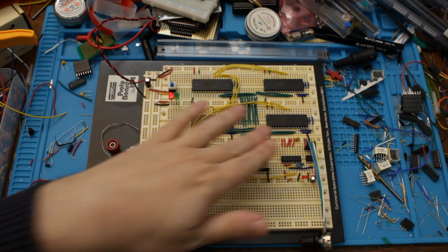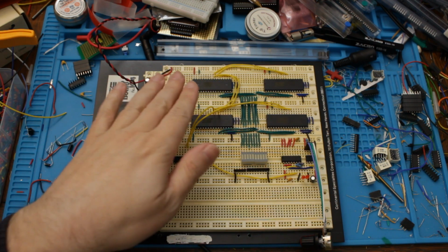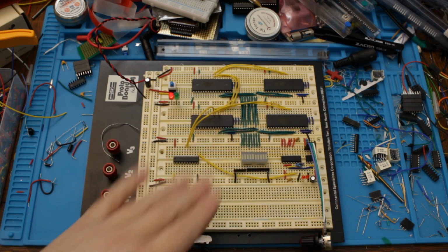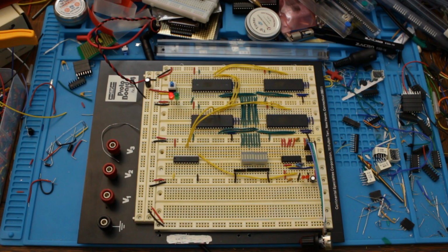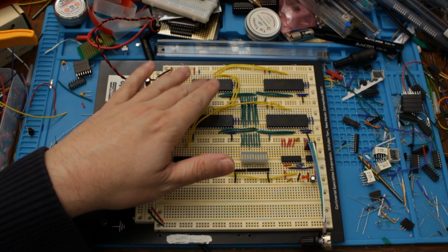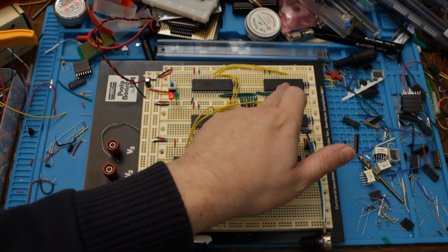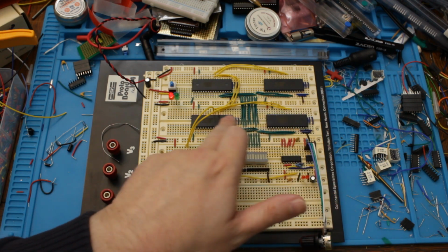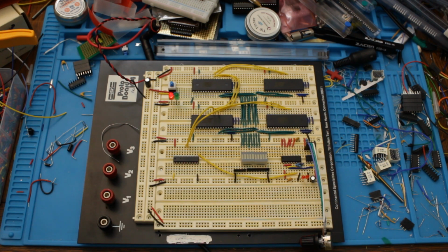As for the EEPROMs, I have pre-programmed them so that each EEPROM has 1 byte value in all of its locations. So every single memory location is going to show up the same instruction here. Remember that each EEPROM holds a quarter of each instruction, so the low byte of each instruction I think is in this one, then the next byte up is in this one, then the next byte up in this one, and the next byte up in this one.